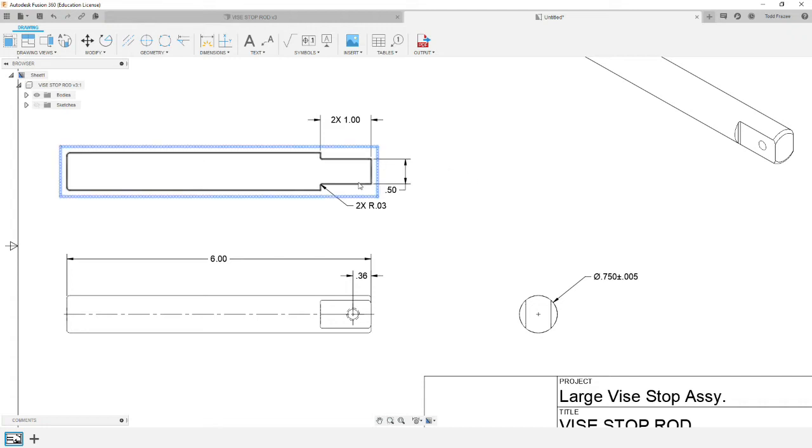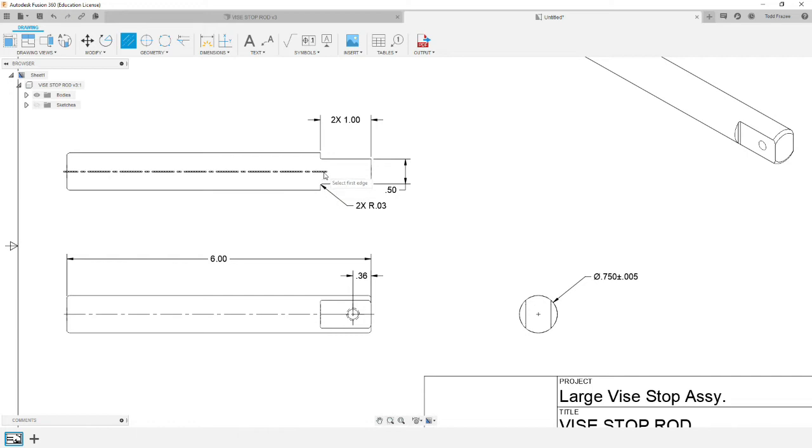We haven't placed the dimension on where the position of this 1/2 inch is. So let's take that off center line. We'll draw a center line first. We'll drag the center line all the way to the end of the part, and that'll allow us to dimension from center line to the edge, a 1/4 inch dimension.